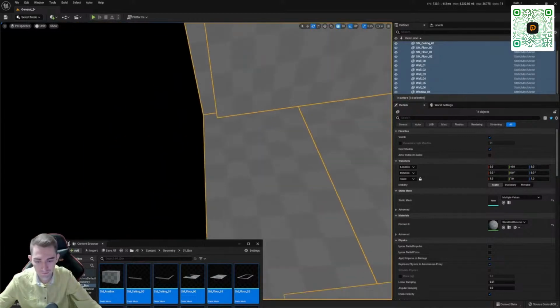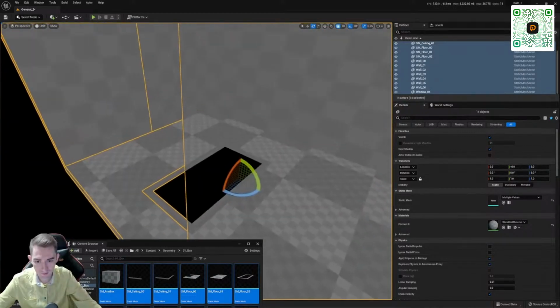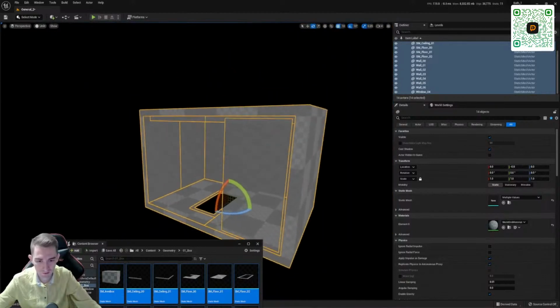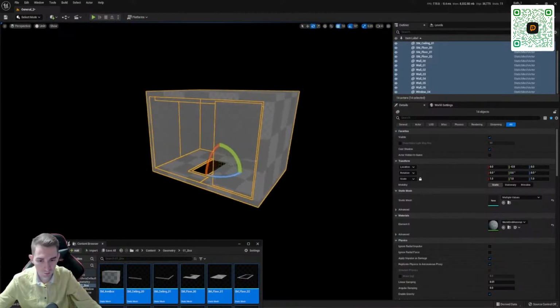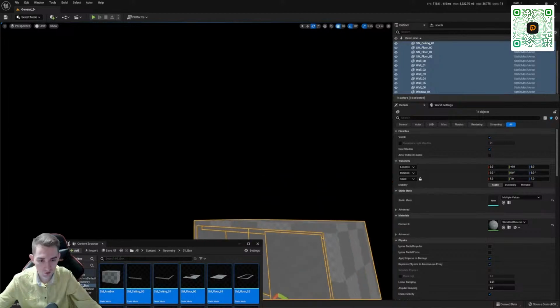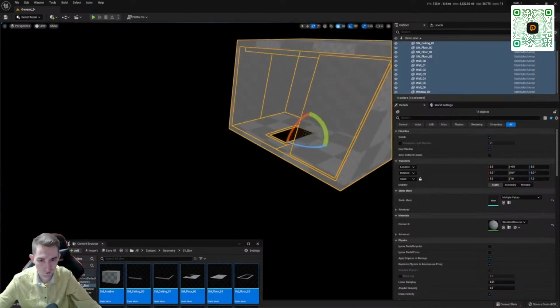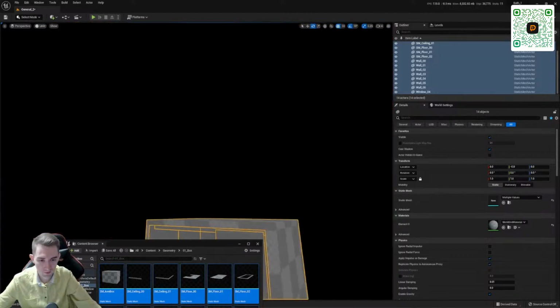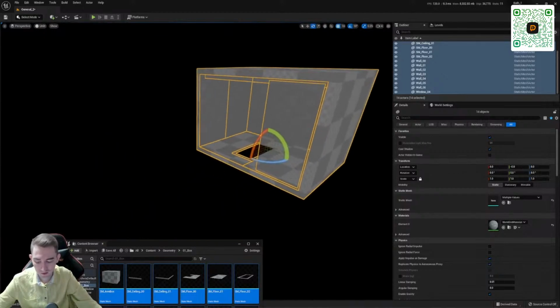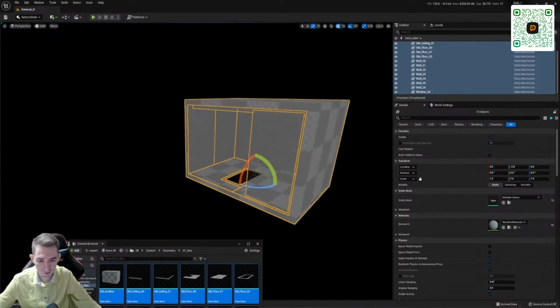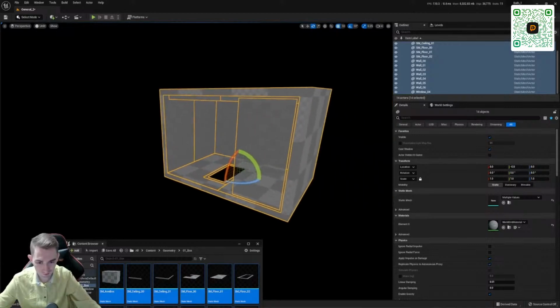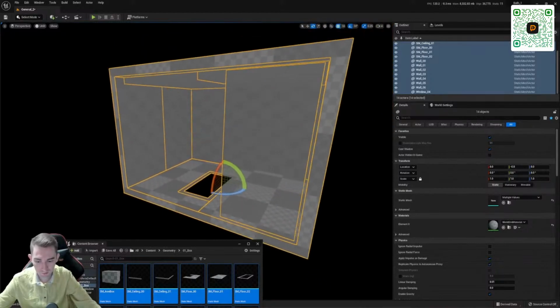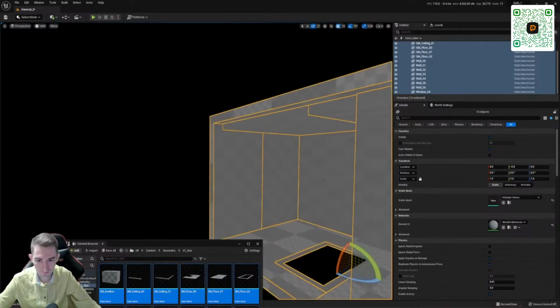Great. So now, by the way, how to fly in the camera, that is, to fly in the viewport. In order to fly in the viewport, we hold the right button and can move like this, as if to look around. If we hold down the right button, as in a game, we move with W, A, S, D, that is, forward, backward, left, right. Those who play games know that Shift speeds us up.